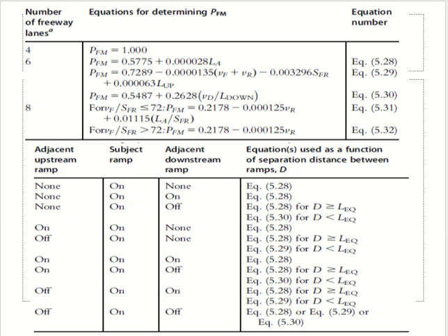Okay, L up, and L down means distance to the next. Upstream, downstream. Up and down is upstream before, downstream after. So I need 3 things here. I should know the 2 flow rates. I should know the speed on the free flow on the ramp, and I should know the distance to the previous ramp. Clear? Okay. So you see L up here and you see L down. L down means what? Distance to the next one.